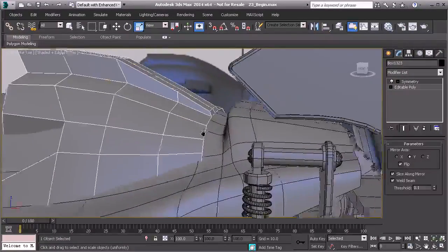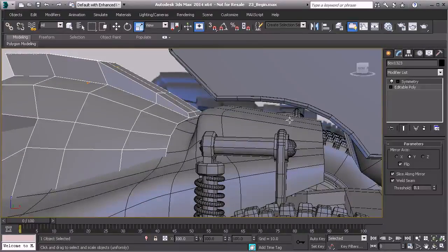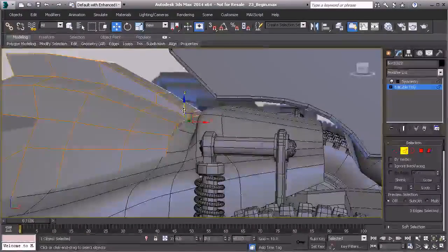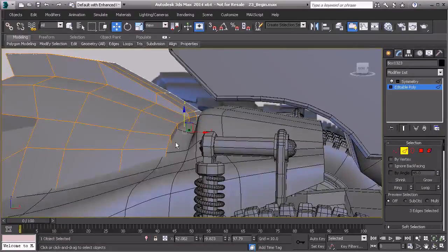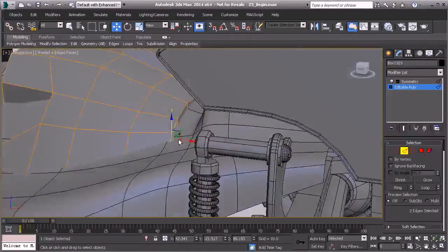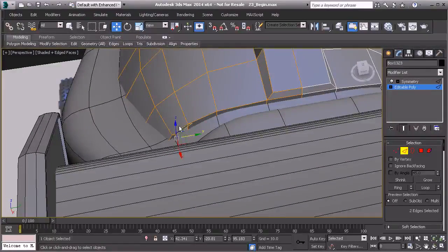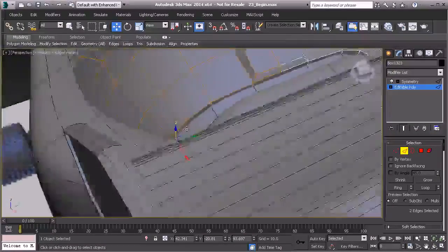Now along the back side, we do need to go ahead and bring that down as well. So let's make sure that we take these, and we'll hold down our move tool, hold down Shift, and drag that down. And then I'm going to take these and drag those over in the Y, and then down in the Z after I've extruded those.